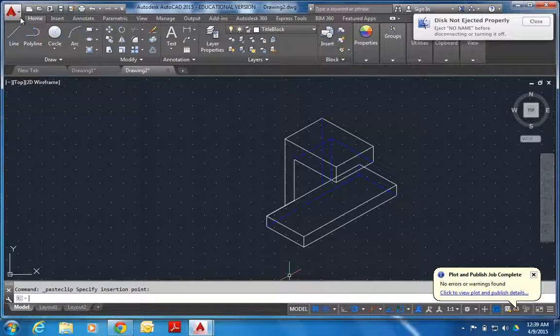ISO circles are a little bit tricky. They're kind of difficult to get started. There's a couple of little tools here that you need to make sure are turned on. The first one being this grid snap. This makes sure that you can snap to an isometric plane.